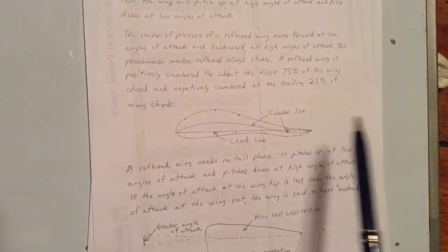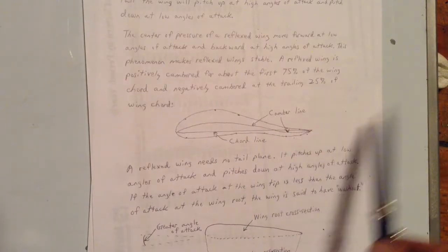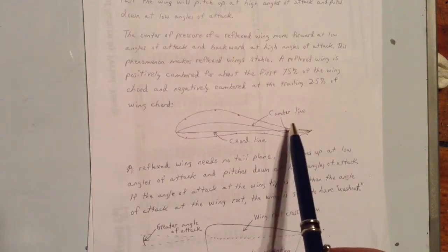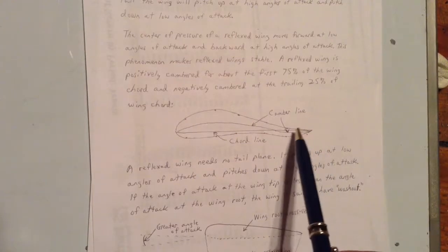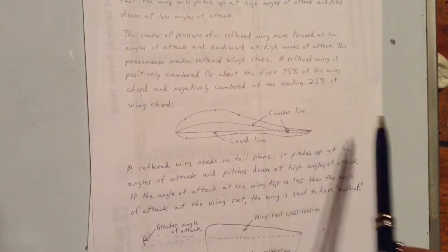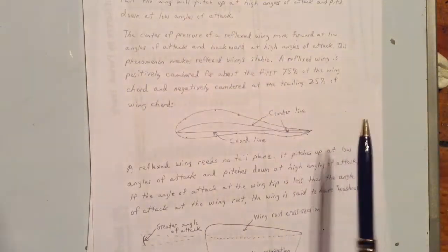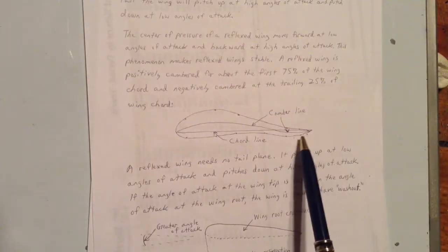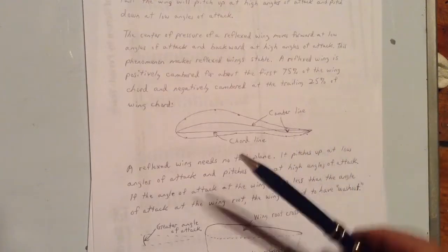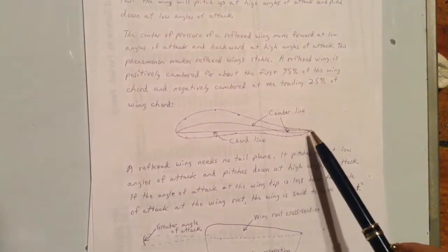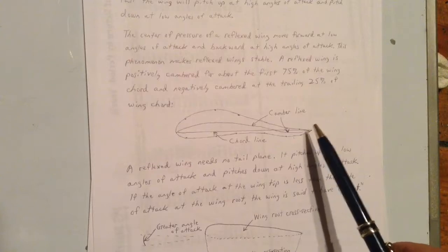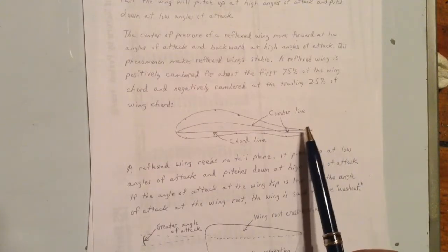And as you can see, this would kind of flip the air back up a little bit, or not let it be thrown down quite so much as it goes past the back of the wing. And as this wing pitches up, you can see why it would lift pretty good back here, and as it pitches down, you can see how this would act kind of like the elevator on an airplane and not give you so much lift at the back of the wing.